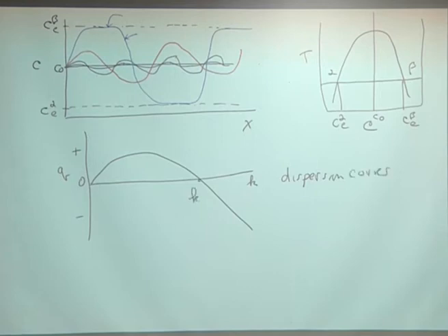You'll notice that for wave numbers greater than k sub c, q is less than 0. Q is less than 0 in that region. Okay? So imagine you're doing spinodal decomposition in a small particle, let's say, and this small particle has a radius r, where r is much, much less than lambda c divided by 2 pi.